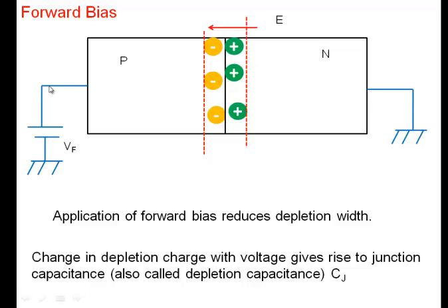Why is it always there? The question that may arise in your mind is, can't I apply 0.85? What if I apply 1 volt? Will I make it negative? Note that as you apply a higher and higher voltage, more and more current begins to flow. When you have 0.7, let's say, the current is fairly large. Now let's say you make it 0.75. How is the current increasing with voltage? Exponentially, remember. So the current becomes very large.